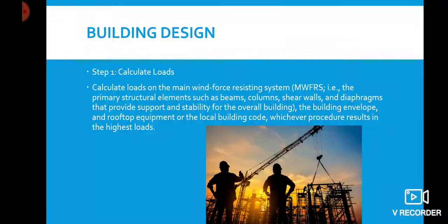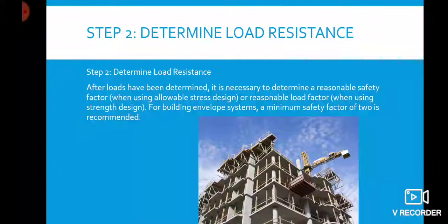Step 2. Determine load resistance. After loads have been determined, it is necessary to determine a reasonable safety factor when using allowable stress design or a reasonable load factor.